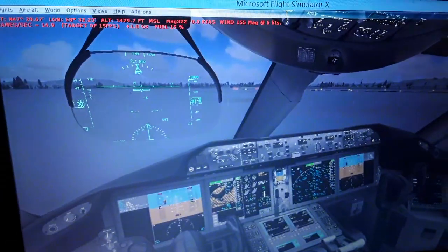The flight management computer is going to give us the takeoff speeds, V1, V-rotate, and V2. We're going to have full takeoff thrust, like 99-100% of the engine's thrust, and V2 is going to be like 130-140 knots, like 250 kilometers an hour. We're going to have a pitch attitude of 9 degrees or less for takeoff, and then we're also going to have the SIDs. The SIDs are the standard instrument departure waypoints and fixes for the initial departure and climb of the aircraft, with altitude and airspeed constraints. We're going to climb to the cruise level at 30,000 feet above sea level.